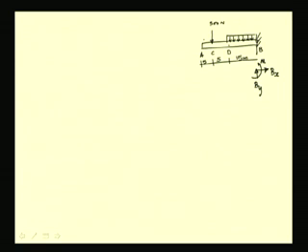So from the equilibrium of this body, we write these equations. The first is summing the force component along the x direction, from which we find that Bx has to be 0, because we do not have any horizontal component of the loading. So Bx has to be 0.